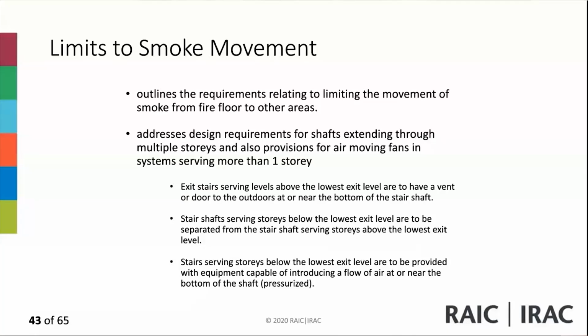We have provisions related to using pressurization, moving air with fans, for stairs serving multiple stories. If they are connected between multiple stories in the basement levels, exit stair shafts serving levels above the lowest exit level are to have a vent to the outdoors at or near the bottom of the stair shaft.